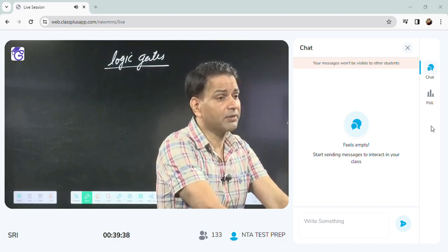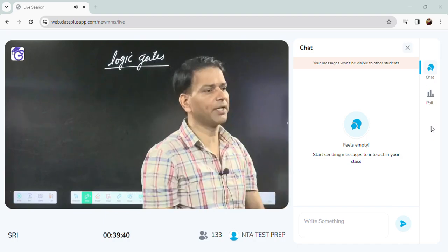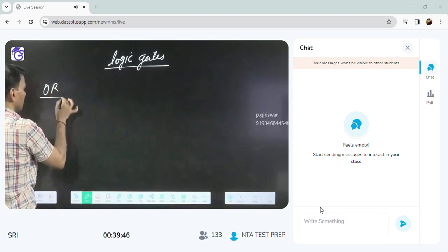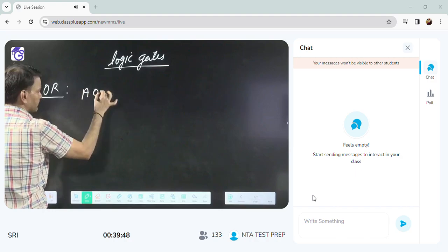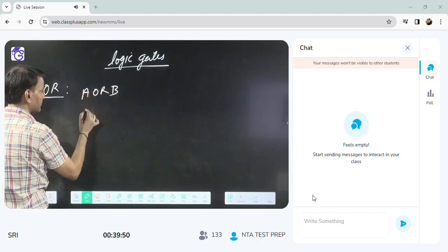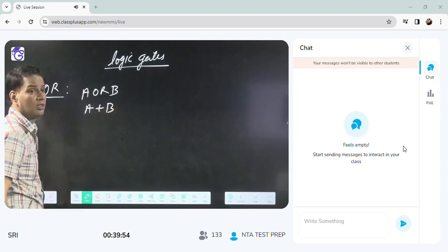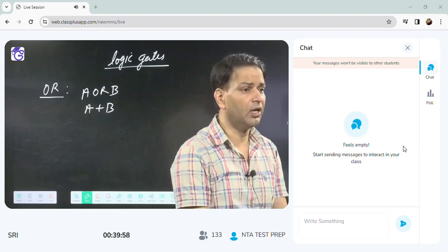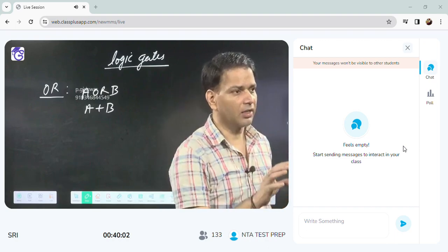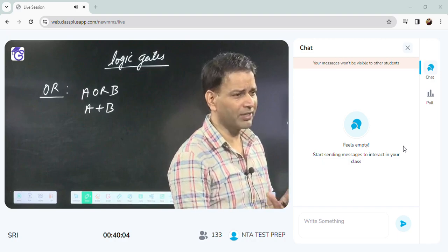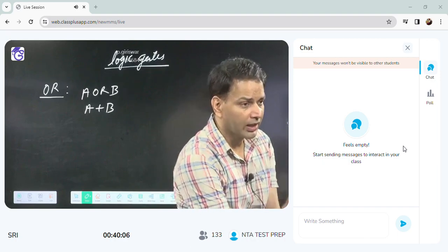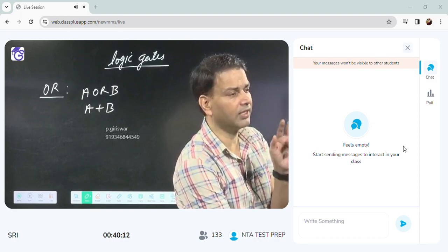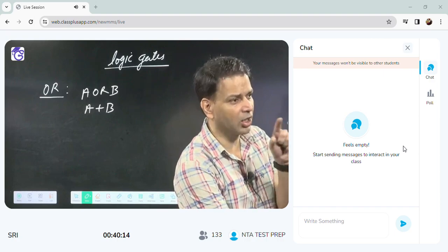What does the OR operation mean? We represent OR by the plus sign. The OR operation means A or B, or I can say A plus B. If A and B are the inputs, and A is high or B is high, then the output will be high.